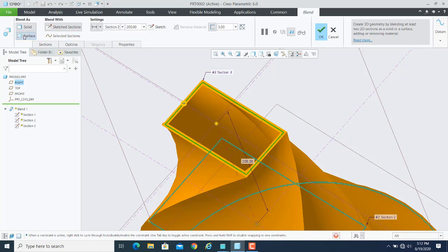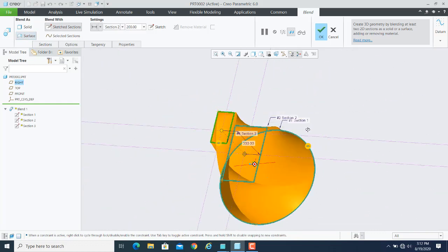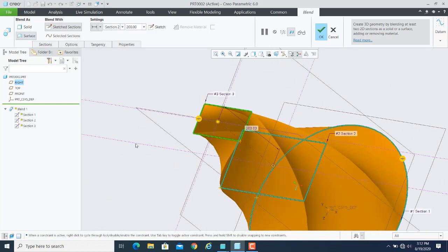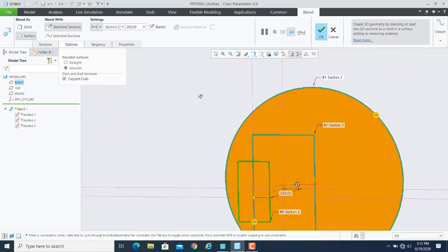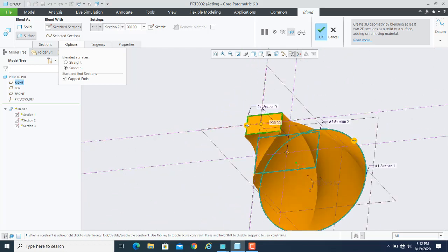And of course, if you are in the surface, so surface में again you will get the open ends, but if you want to close that, again you can go to the options, और ये cap end का surface की जो भी command होगी that will be available. So you can use the cap end option to close those open regions, but still that particular object will be hollow inside.